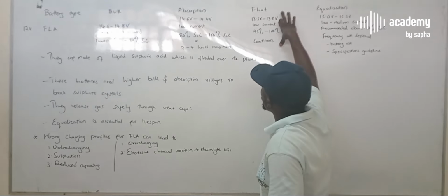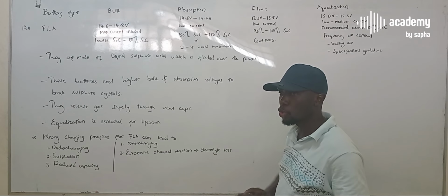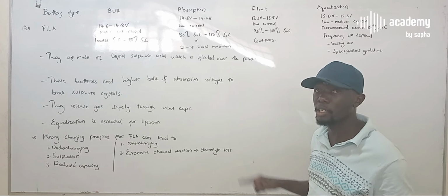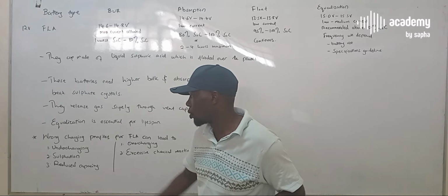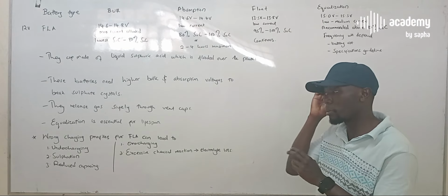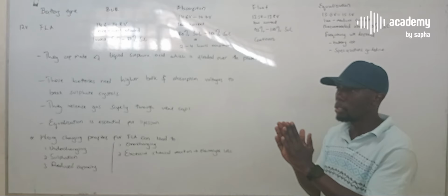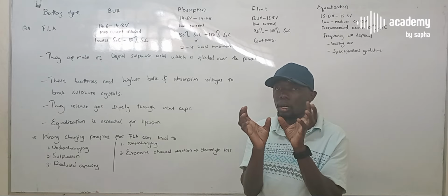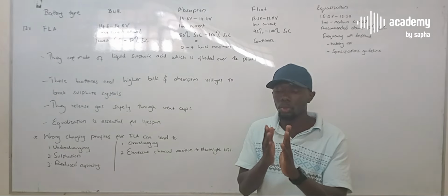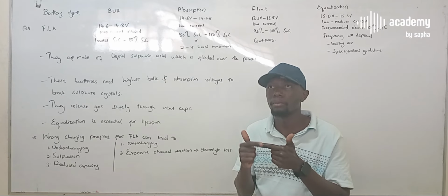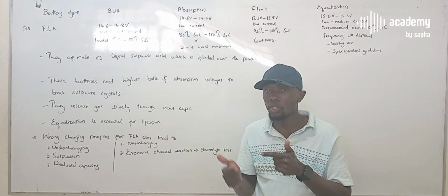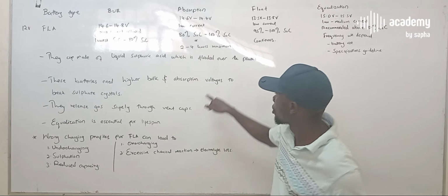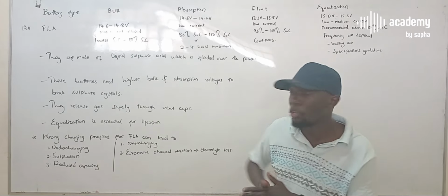So whenever you undercharge this battery, it means that at any given point, not all the battery experiences chemical reaction in entirety. And that leads to sulfation and reduced capacity. The reduced capacity happens because the actual capacity of each cell starts shrinking, because the chemical has bonded on the plates. So the actual charge carrying electrolyte is now not available because it's been bonded on the internal plates of the battery.